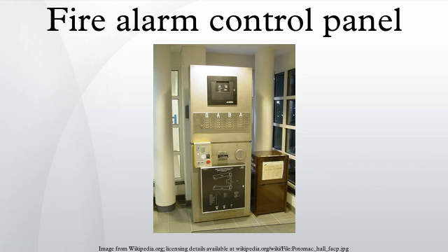This LED can only activate if there is a secondary device hooked into the priority to alarm terminals. This secondary device could be a security system, building management system, or another fire alarm control panel. Depending on how the panel is programmed, the panel's alarms may or may not activate when a condition like this is present. Trouble, also known as fault, or defect.